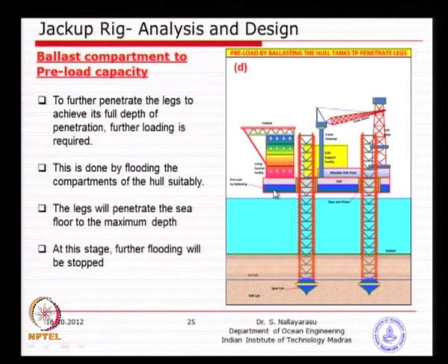Next, basically flooding, by pumping water from the sea. You will have ballast pumps pumping water from the sea and putting it into the hull, and the legs would have sufficiently penetrated if you have made the calculation. That is why every time you go to a new location, you do a borehole, get the soil data, and calculate the weight required and the bearing capacity. Of course, we will learn all this bearing capacity calculation in the next semester in the foundations course. I do not think we want to introduce that now. Basically, a simple bearing capacity calculation makes sure of the weight required in the hull to get a penetration of so many meters.